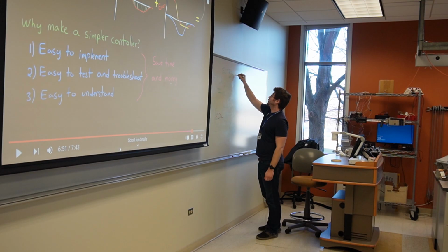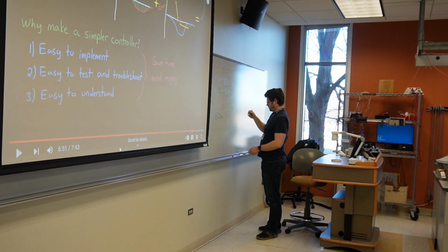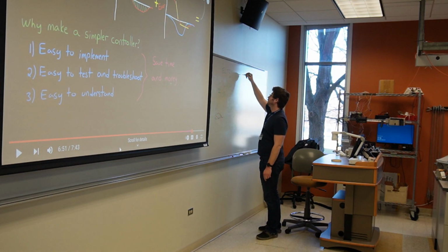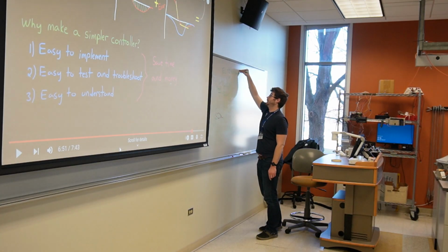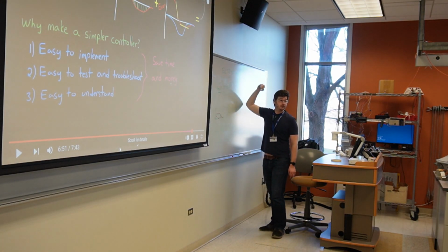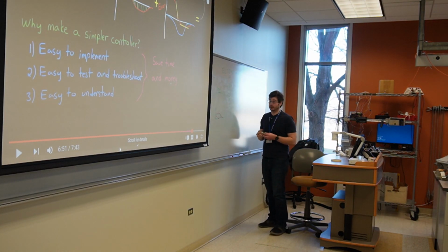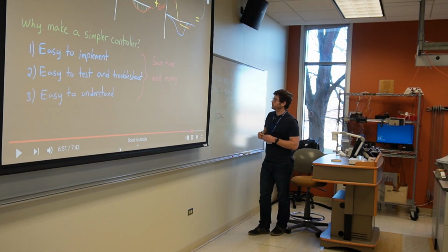So what'll happen is we'll have this process control. We'll be coming along here, and the I controller will go, oh, we're a little bit off. I'm getting mad. And then it goes, oh, we're a little bit over. All right, we should go down. Oh, I'm a little bit under. We should go up. And then it keeps kind of going like that. It keeps swinging, so oscillating. It's one thing that can happen with the I term.